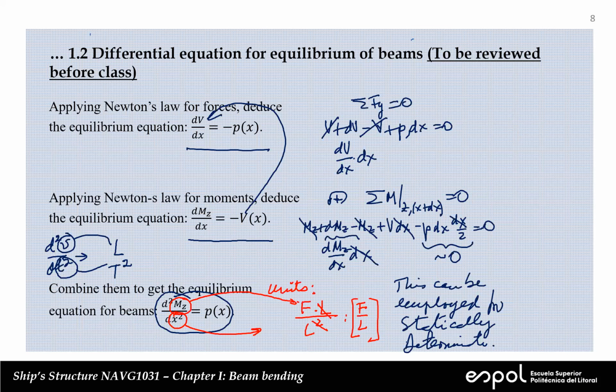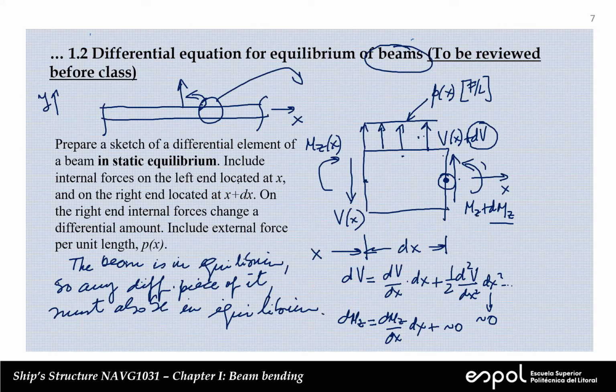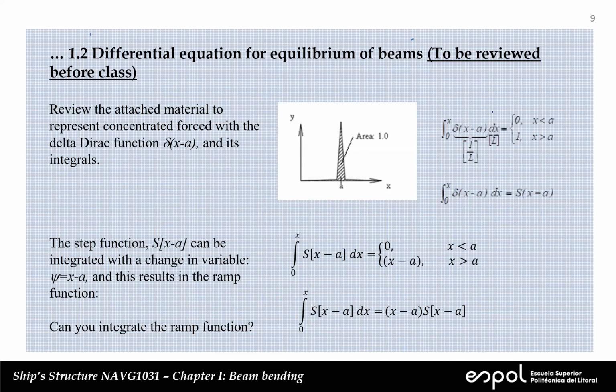Now here, let me go back. This is the external force, this is p of x, and it's expressed as force per unit length. That's what it represents. The problem is that in many cases we have concentrated forces, very often. And when we have concentrated forces, usually the structural requirements from the structure are very high. So it's very interesting to be able to analyze this type of situation. What can we do in that case? There are many ways. This is only one way, uses Popov, and that's what we use here.